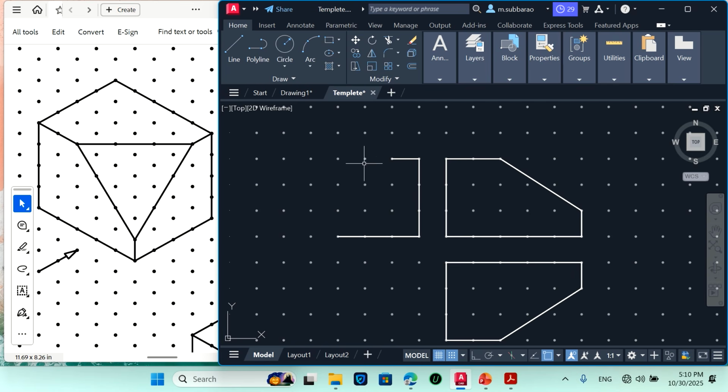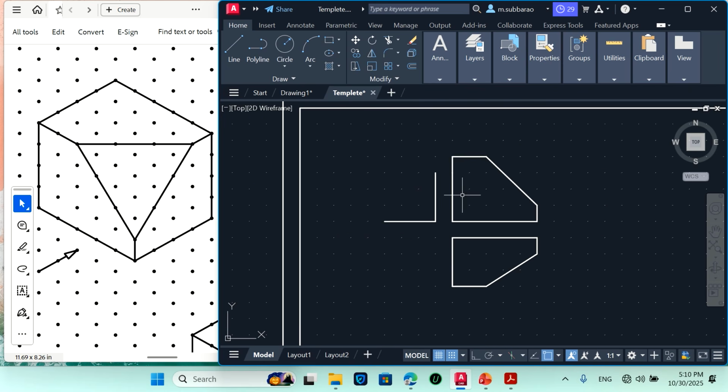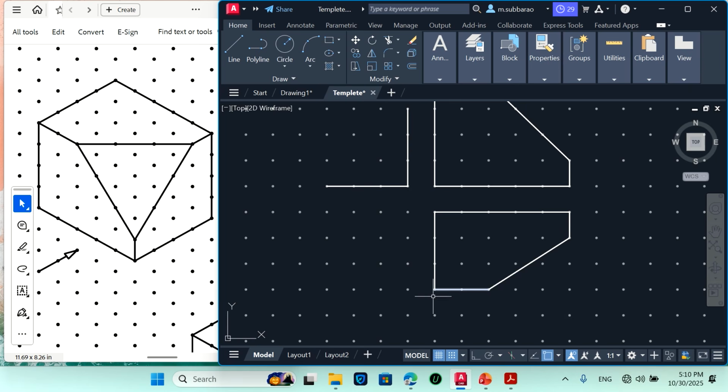This height is 40 mm, but I have taken only 30 mm. So I will draw one more grid. Then if I draw the 20 mm here, this becomes the front view, and in the top view also this is 40 mm. So I have taken only 30 mm by mistake. So I will be taking one more grid, and then the 20 mm, and I will complete.